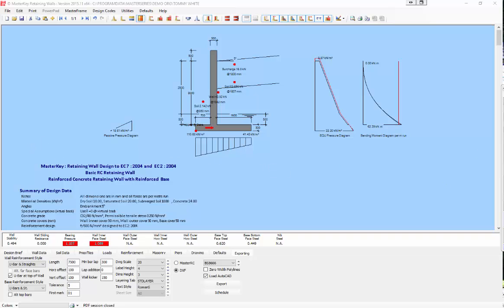That's just a common sense warning. It's a rule of thumb, but I think it's quite a wise rule of thumb to say that you don't want a wall that's constantly got uplift here, because if the wall is going to rock and it's going to suddenly loosen the soil here with this being on pressure and that having no pressure, you are going to slowly over time get that wall tilting. So it's not a good idea to have a wall with a lot of uplift on it.